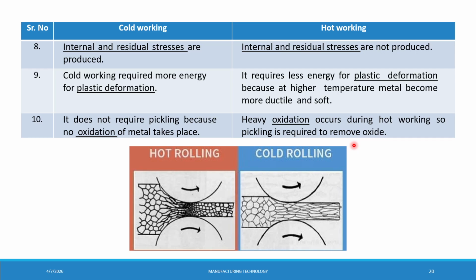I hope the students have understood the processes and the way that the microstructure is created in the components. So whenever you are utilizing components from the market, you have to understand whether it is cold rolled or hot rolled. In general, it is hot rolled, but in certain specific places, you would come across cold rolled steel. So you have to understand that they have a much harder work surface. Okay, so whenever you try to cut it or you try to mark it, it will be significantly harder as compared to materials which have been hot rolled.